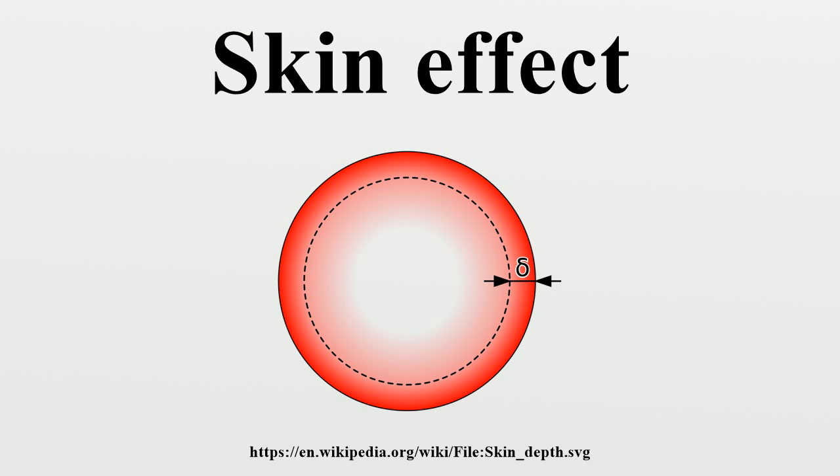High voltage, high current overhead power lines often use aluminum cable with a steel reinforcing core. The high resistance of the steel core is of no consequence since it is located far below the skin depth where essentially no AC current flows.